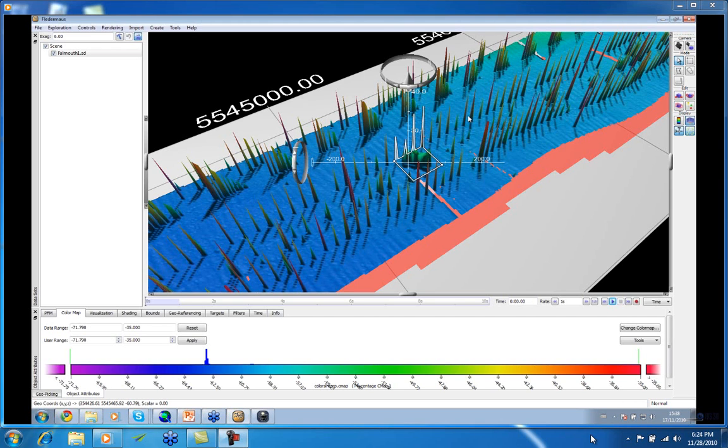The other thing was, until 7.2.1a, there was a problem, well, not a problem, but we were using the version 6 Caris libraries, not the version 7 one. So if you had version 7 on, then you had to put in version 6 to enable it to be used with Fledermaus. We have found, however, that Caris have also changed a lot of their library structure at the moment. So I would hang fire on 7.2.1a until 7.2.1b is out, because they've changed the way they store variants.